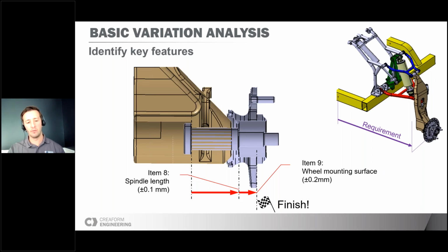And defining that value is really at the beginning of the design, when you haven't had the discussions with your suppliers yet. I mean, you can find quite easily the process capabilities of different kinds of manufacturing processes. So these are some assumptions, but when you start sending some preliminary drawings or have some discussions, you can quickly ask your suppliers, okay, I have this kind of part, what kind of accuracy do you think you'll have, and you can update your stack-up quite easily.